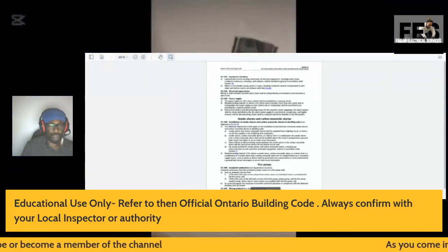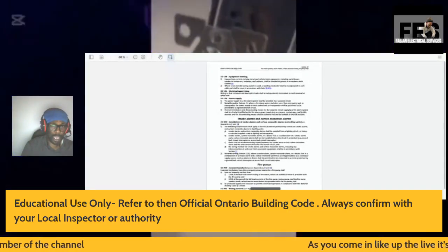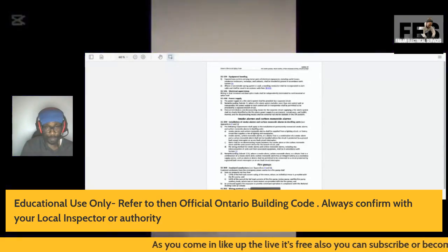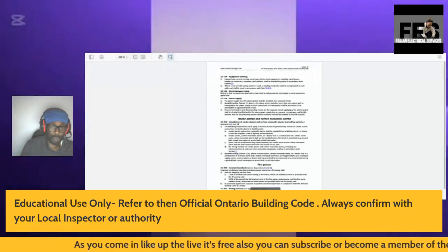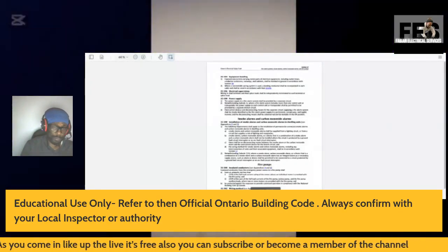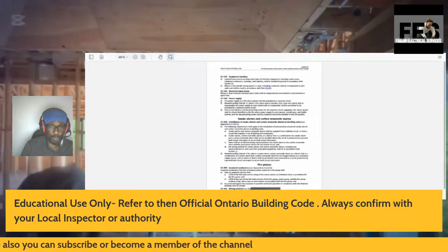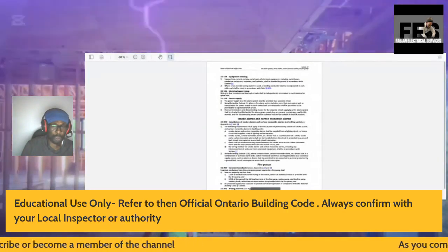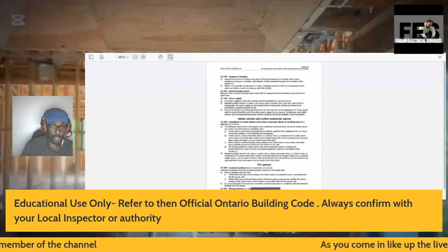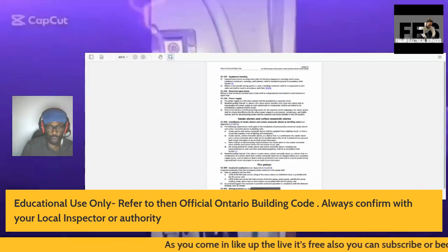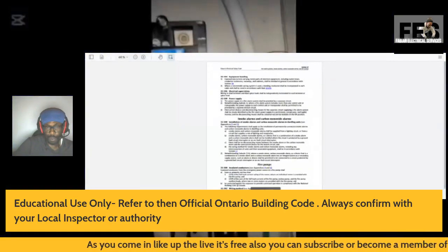If your battery is working, it will signal. Also, make sure that your smoke alarm, smoke detector is not expired. Max 7 years for the normal smoke detectors and 10 years for the other kind of the strobe-like smoke detectors.